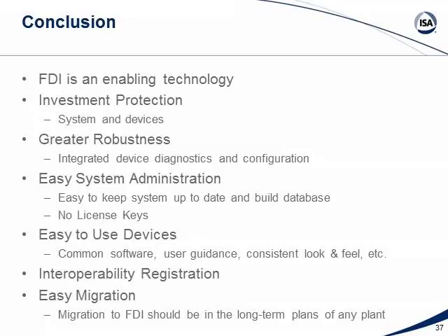FDI deals with that whole version management. What files have to go with which device? What happens when I get new files? Do they replace, upgrade? All those lifecycle scenarios have been fully considered as part of FDI. It's a real robust lifecycle, and that ultimately is going to make device integration much more robust and much easier.